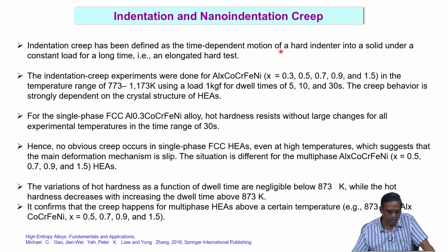So, indentation creep has been identified as a time dependent motion of a hard indenter into the solid under a constant load for a long time. That is an elongated hardness test. Anything we talk about as creep means a time dependent phenomenon, right? So, time dependent deformation. We will talk about creep behavior tomorrow when I show the high temperature behavior of this material. But we are talking about this at room temperature or high temperature both.